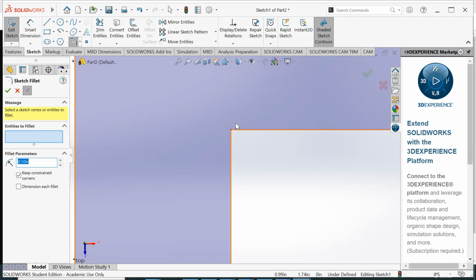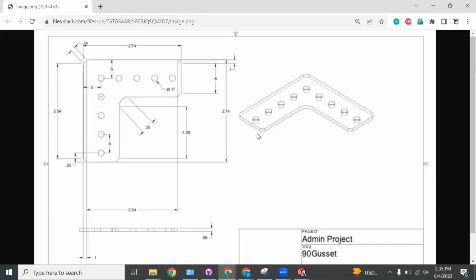So it can't have this intersection right there, that 90 degrees, just because, again, the piece is kind of like a drill bit, which is rounded. So if you're spinning that really fast, you can get close to an angle, but you can't get that precise 90 degrees, and you have to give it a slight rounded edge, or else we literally cannot manufacture that part. So that's why we use a fillet. Let's see how to work with one.